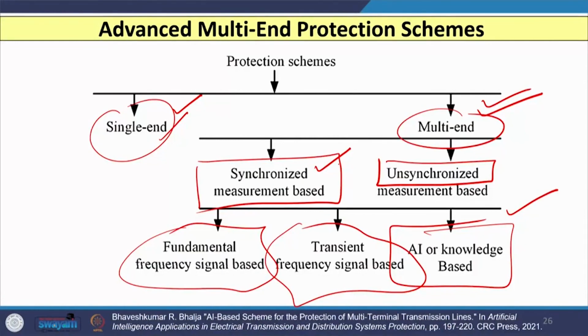And the third scheme which is used nowadays is based on synchronized measurements using synchrophasors. So, we have GPS using which we can take synchronized measurements at different buses. So, this is widely used for the protection of multi-terminal transmission lines.